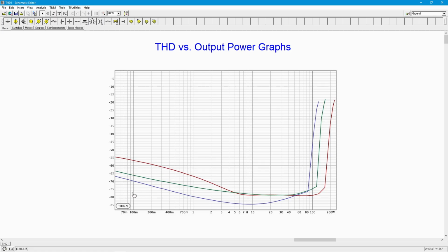So usually for a Class A amplifier, like the one that we were simulating just a moment ago, you'll see a value that will increase, more like this. You might have an increase at the bottom end here due to noise, but more of a consistent rise because the nonlinearities just get worse and worse as the signal grows. Right?